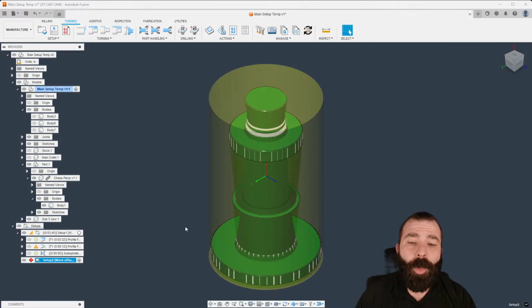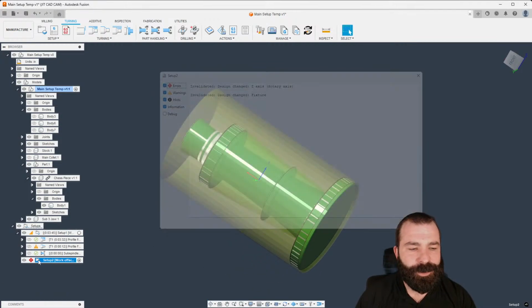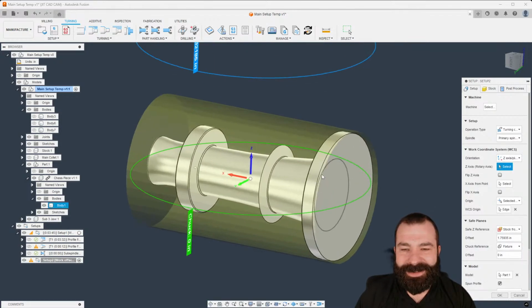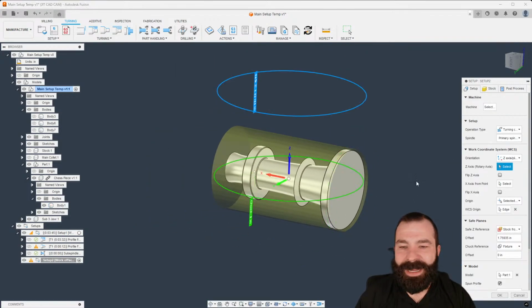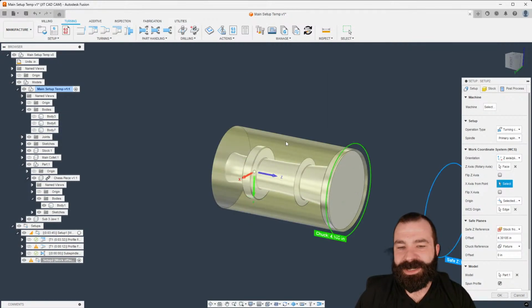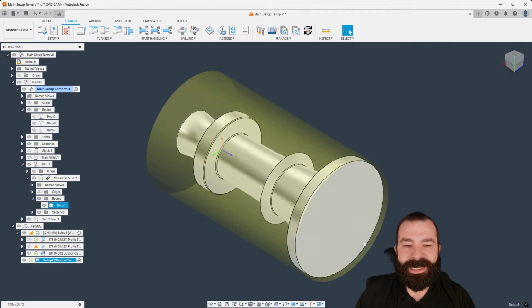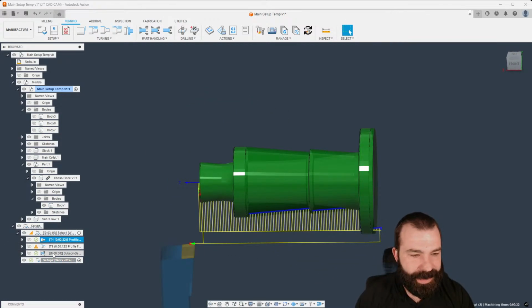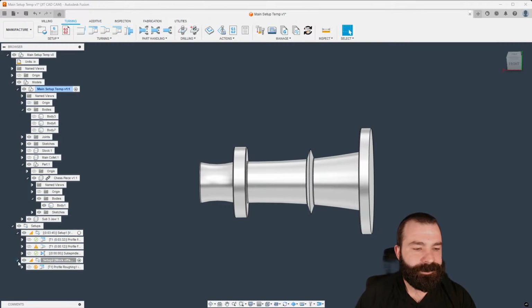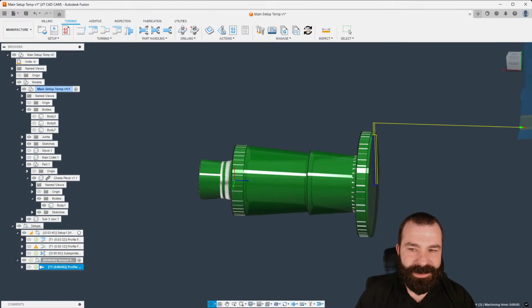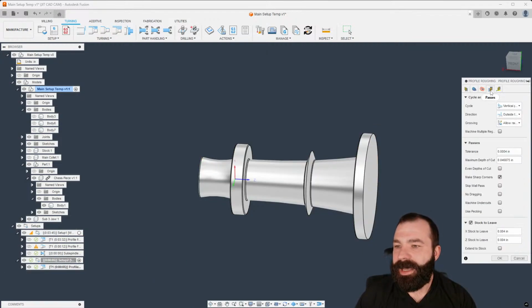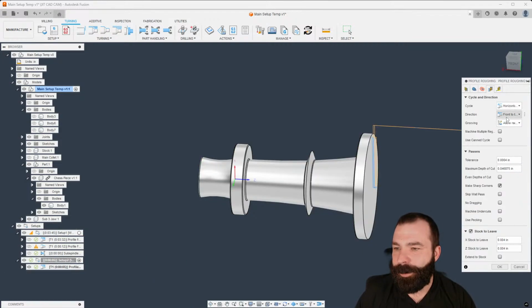When we flip over to machine our backside, of course, our setup is all wacky here. Let's go ahead and edit this. You need a Z-axis of rotation, of course. I didn't define that on the model. For those of you out there wondering, you would always define things off known features like the stock. Getting our part all lined back up for setup 2. Let's go ahead and copy a path down. We should have axial grooving. Oh, I went ahead and copied that. And we're going to change back to horizontal passes.